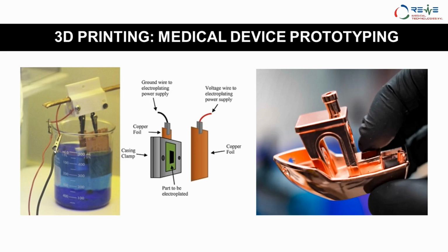And once you have that conductive layer and it has a specific level of resistance on it, you have to file it and get a very smooth finish before you place it inside. You can then conduct the electroplating process in which the metal goes and gets coated on top of the product, and you get this sort of finish. You can actually get this finish in the first go as well if your process is very optimized. This is very good for aesthetics, and it adds a lot of strength to the part as well.